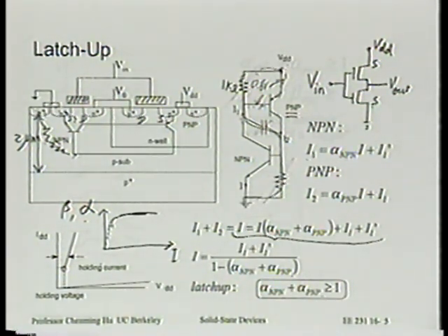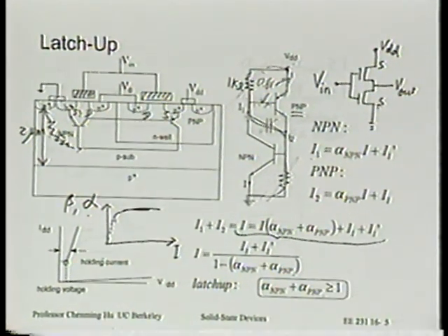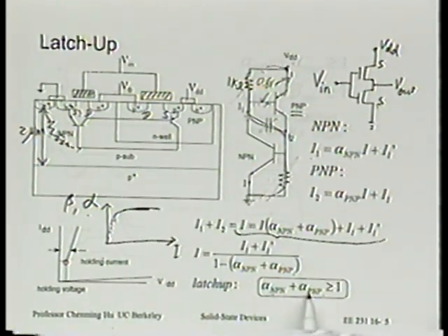It's okay? All right. Finally, let me mention one other thing. This is more realistic now for more recent technology. In the past, it's not so realistic. Turns out latch-up behavior, if you plot the IV curve, has 2 branches. One in the off state, that is before this condition is satisfied as a result of a trigger. The circuit is just an open circuit. That's what we want the CMOS circuit to be like.